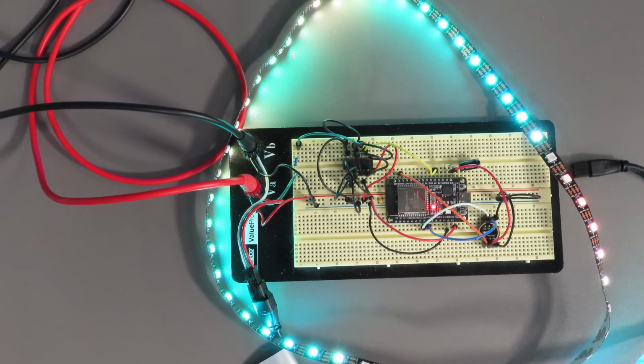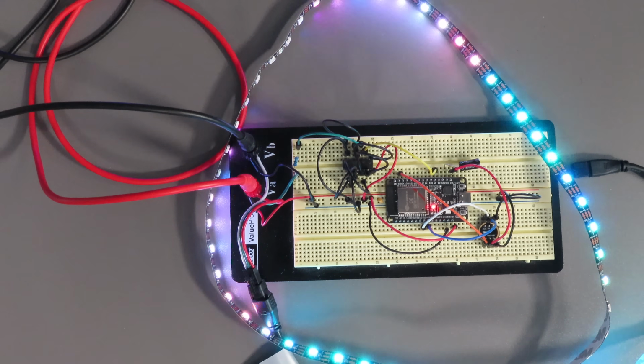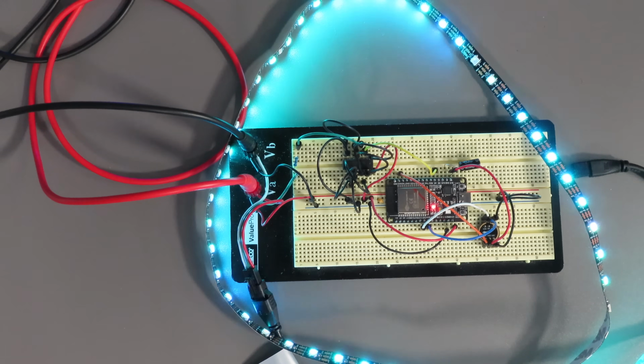Now, there are instructions on the WLED website for using things other than microphones as an input. For example, if you want to use the output of an audio amplifier, they will show you how you do that. Essentially, you feed it into the ESP32's analog to digital converter, and it works that way. You can also use analog microphones that way too. So audio reactive adds just another dimension to the amazing things that you can do with WLED.